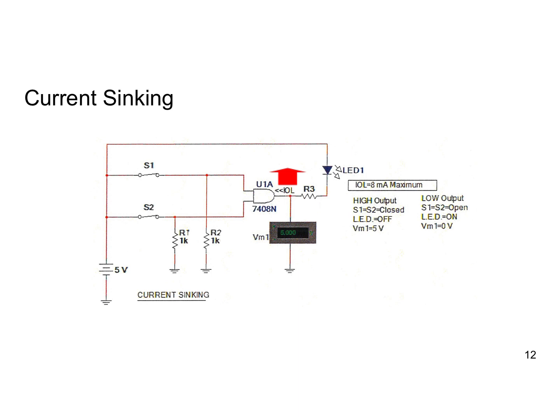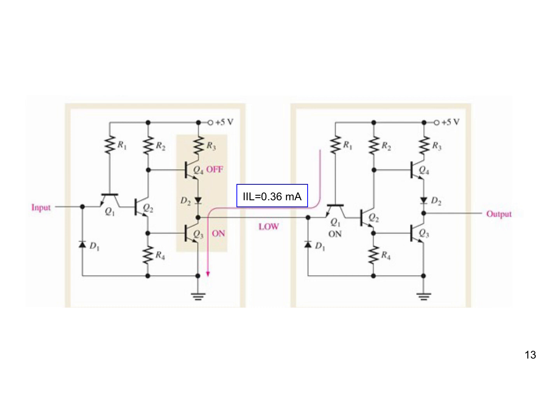Okay, again, just using switches. These are still like the pull down resistors. Current's going to be flowing like that, and then internal to the transistor, you can see current's going to flow, forward bias there. This transistor has been turned on. It's going to flow, just sink, and then down to the ground.